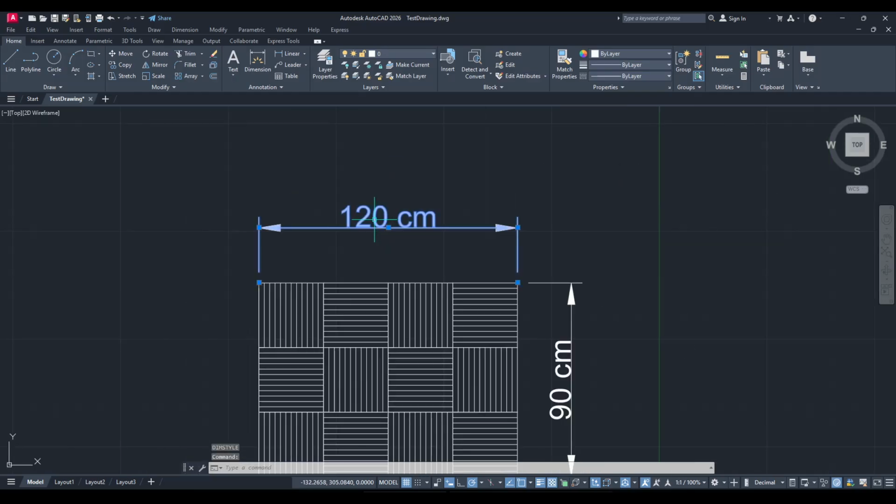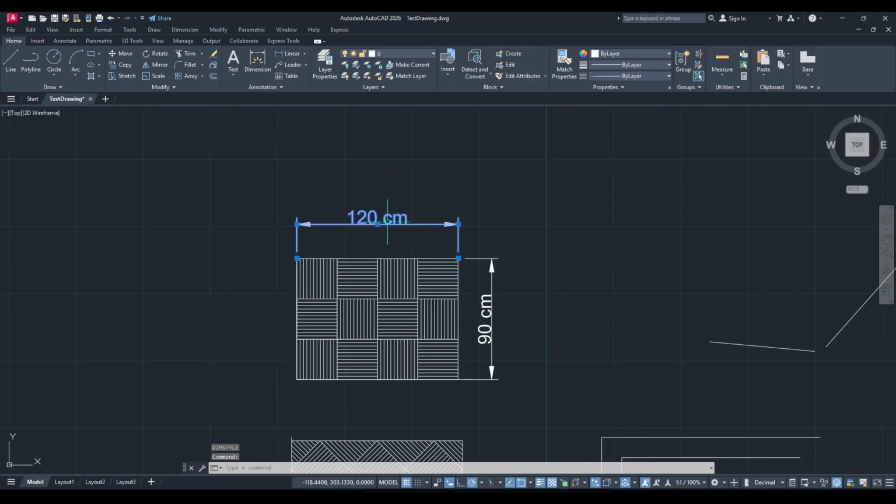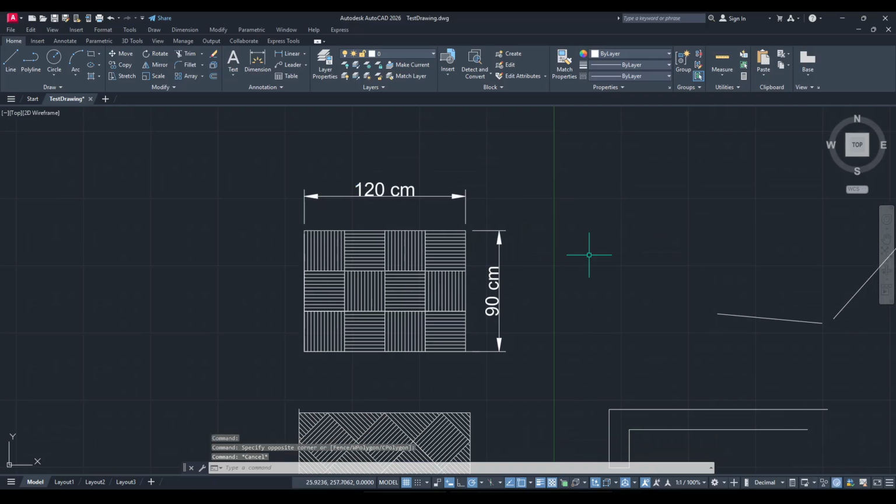Keep in mind, adding a suffix is purely a display choice. It does not convert the measurement itself. It simply labels the number so readers understand the intended unit. If your drawing contains multiple dimension styles, repeat this process for each one you actively use.